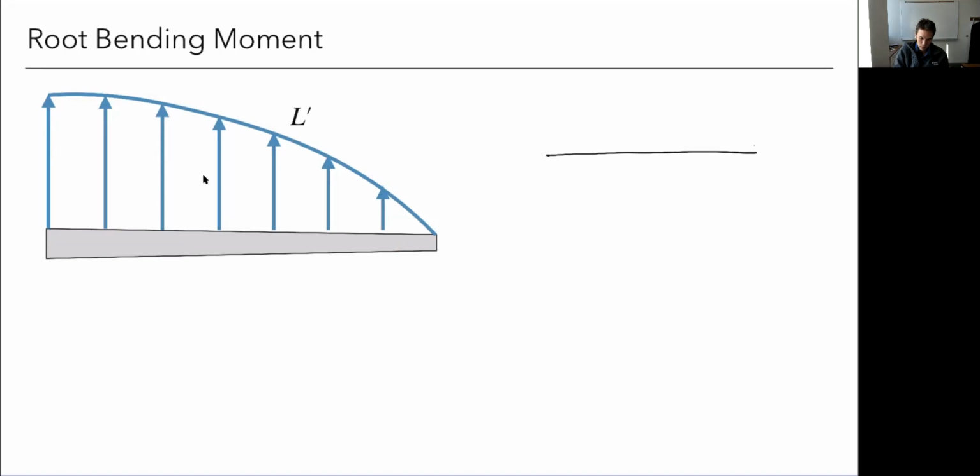Let's say I added a winglet, and if I just turn the winglet so that the load was exactly pointed towards the root, we would say it contributes nothing to the root bending moment, because the moment arm is 0. But of course, that had to have added some weight, and it's adding loads and bending stress. So it's not really a good metric in general, but it's a good motivator of the primary physics here, at least for this conceptual discussion.